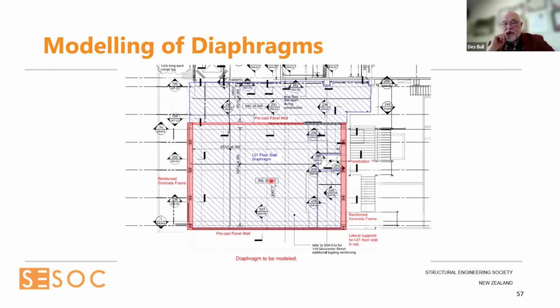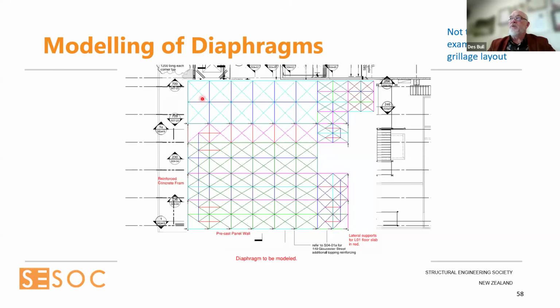I just want to talk a little bit about one of the modelling techniques that's available out there. This is walls up here, walls here, concrete moment resisting frame here with structural steel and columns. It's an older building, and an annex sort of floor area flapping out here outside the main structure. I'll just point out, heaven forbid, this was in the early days. This is not a really good example of how to set up a grillage in terms of the squares. I've broken some of my own rules from 2 slides ago. But what I want to focus on is the next few slides.